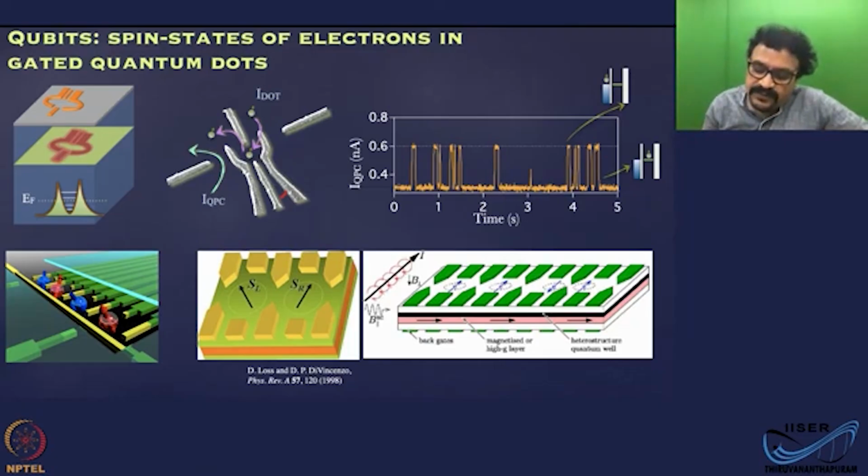Anyway, you can detect that by looking at the signal of the QPC or the current of the QPC. Whenever that current abruptly changes, that corresponds to an electron tunneling event into or out of the dot. So now what you have is a system where you can trap electrons, and you also have other bells and whistles to detect the electron tunneling events and the electronic configuration of the dot.